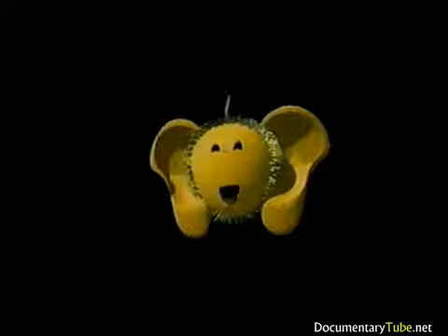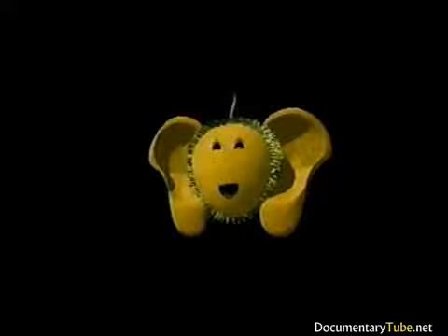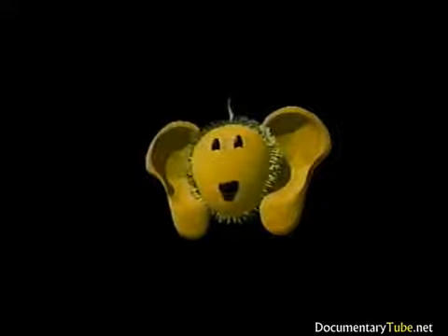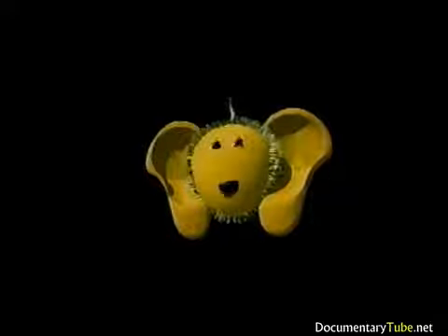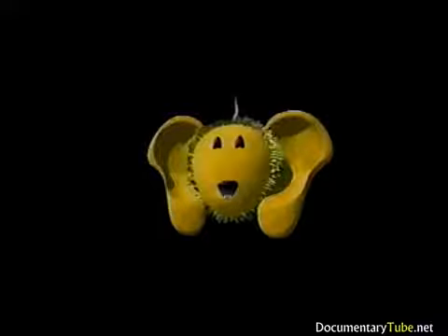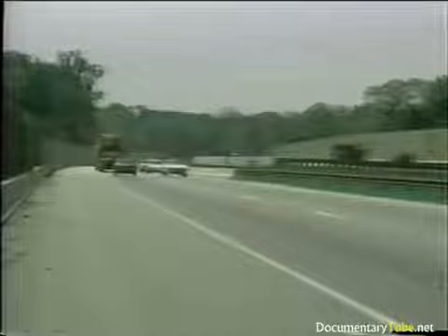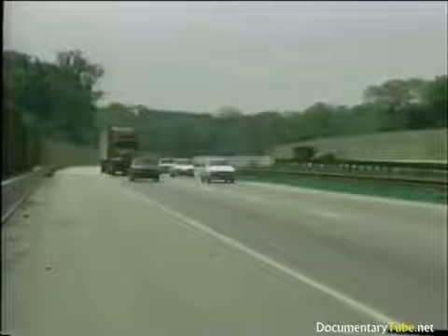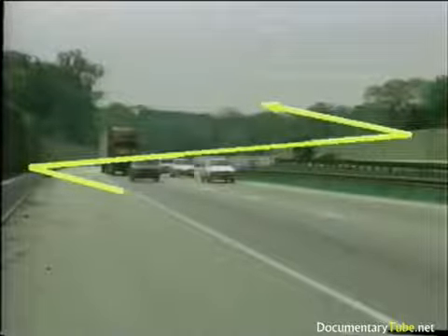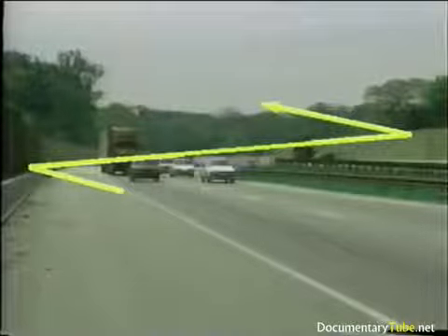The signature of the reflected sound may differ from that of the source due to a change in frequency content upon reflection. If we have parallel barriers instead of just a barrier on one side of the highway, the situation becomes much more complicated. For parallel barriers, sound may reflect back and forth across the roadway many times before ultimately progressing outwards toward nearby receivers. The multiple reflections increase the sound level at nearby receivers and can reduce insertion loss provided by either wall alone by 2 to 6 dB.